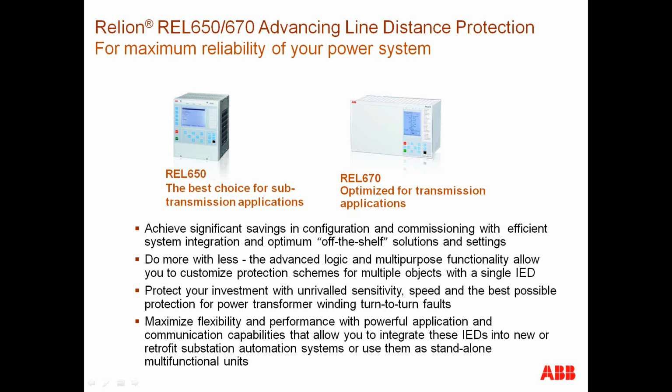Now, if the source behind me that's weak changes and becomes strong, then you block the weak feed logic and just allow it to trip normally. So it depends on if occasionally you have a weak feed and other times you have a strong feed, then it doesn't matter, because if you sense a forward fault, you block the weak feed logic typically. I hope that addressed the question.